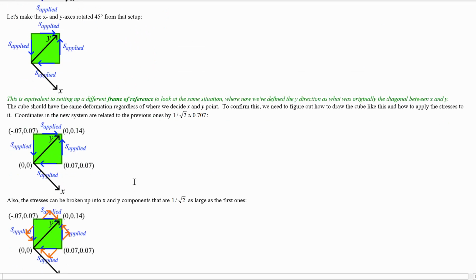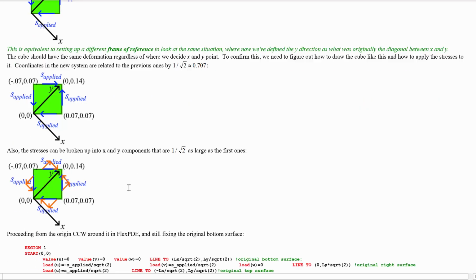So if you take a brittle material and put it into pure shear, it will tend to cleave at 45 degrees off from the direction of the shear forces, because that's where it ends up being in the highest tensile stress.